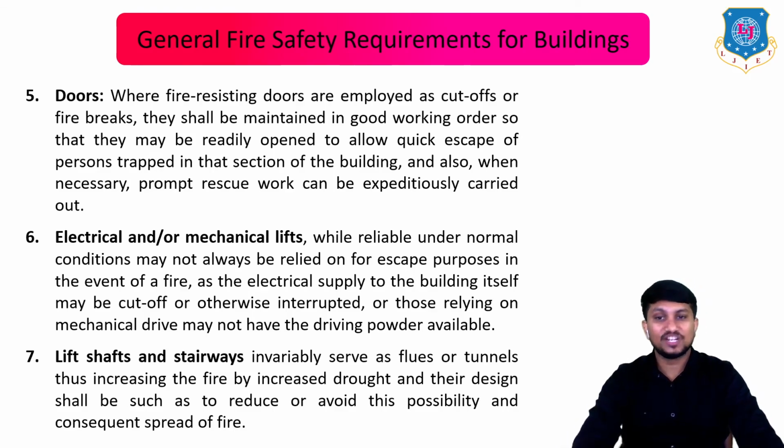Lift shafts and stairways invariably serve as flues or tunnels, thus increasing the fire by increased draughts, and their design shall be such as to reduce or avoid this possibility and consequent spread of fire. Okay, so this point is also considered.